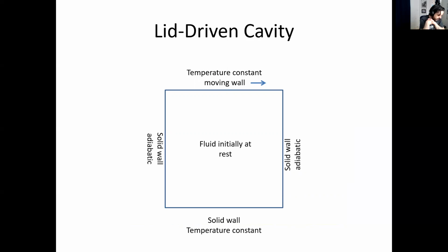And it's included in that way that I have a constant temperature on top and a constant temperature on the bottom, and on the side walls I have an adiabatic condition. That will be exactly the same as for the Rayleigh-Benard convection. It actually turns out, we will see that in a second also, that the inclusion of the temperature on its own serves as a nice way of visualizing how the motion of the flow is actually happening.